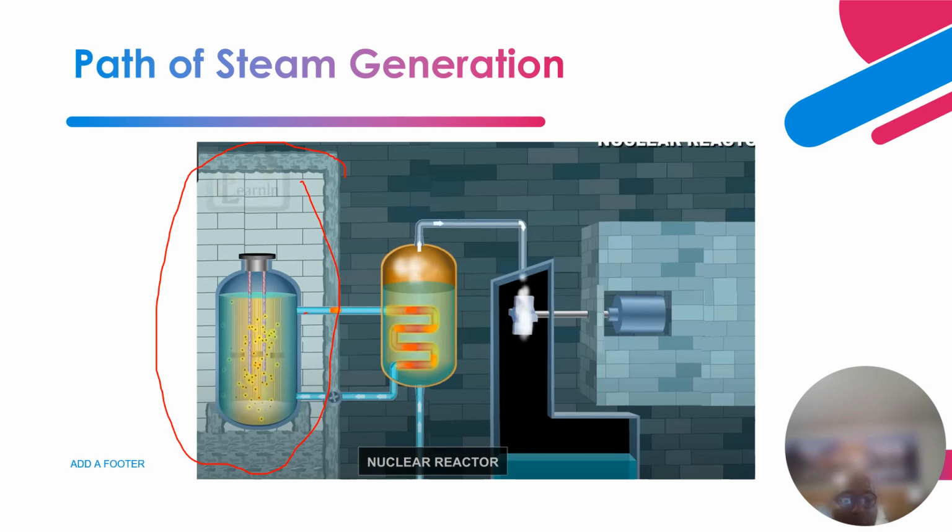That steam flows through these coils in the closed loop part, and this steam generator also has water in it. The thermal energy is transferred to this water to create steam, and the drier steam moves up into this piping and comes into the turbine and rotates the turbine, and from there it rotates the generator.